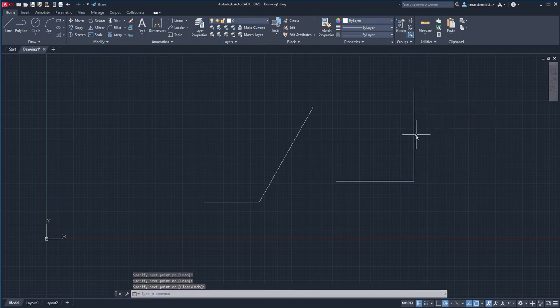Now let's say you want to turn polar tracking off completely. I'll show you how it's done and essentially what happens. We just move down to the status bar, left click, and now it's turned off. Now watch this. I'll select my line tool again, left click, begin one anywhere, left click, and now look, it's not giving us any sort of indication as to where the vector is in terms of degree direction. So that's what essentially happens, and that's what you get when you turn that off.